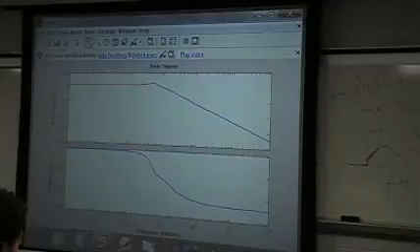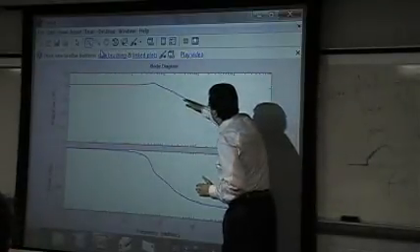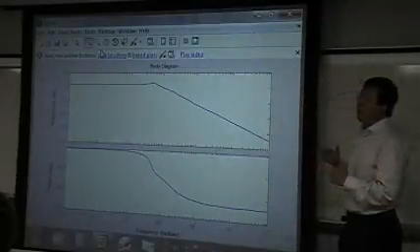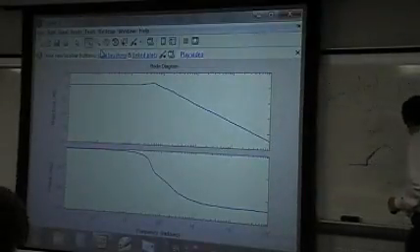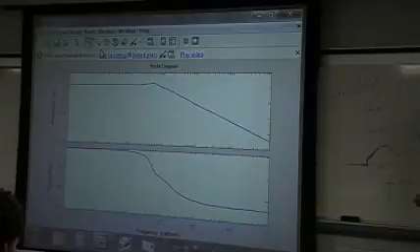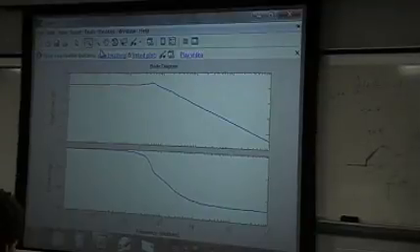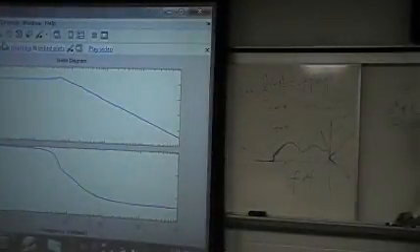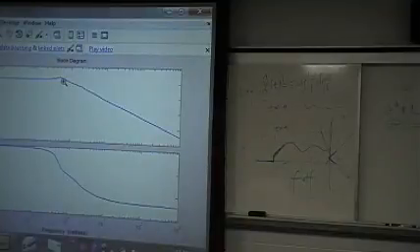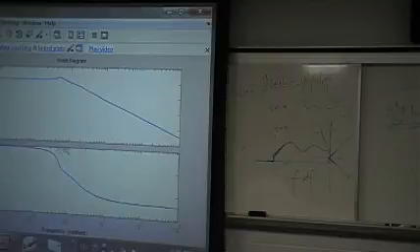And if you zoom in on certain areas, you will see that the lines have a slope which is not 20 times k dB per decade. The k here might be a non-integer number, so the slope may not be the same as for integer order systems.